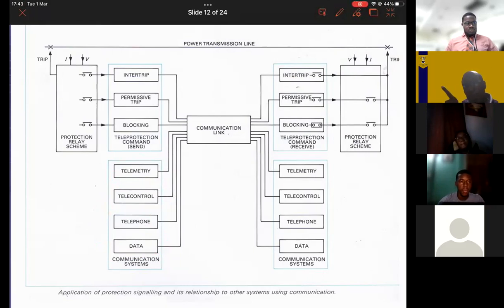What you would have is the line opening. What the engineers would then have to do is to track the line. So you might say, well, they have a power cut due to an open line, a fault on the line, and breakers open. You can't reclose them because the fault is there, so you now have to physically go and clear the fault.